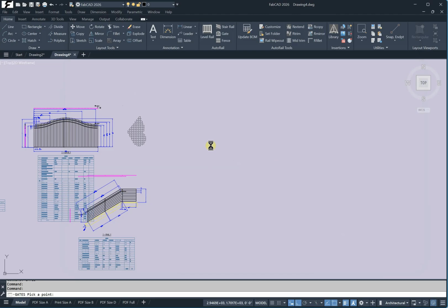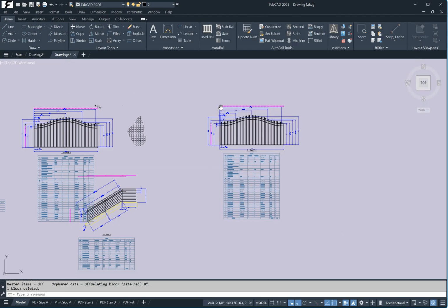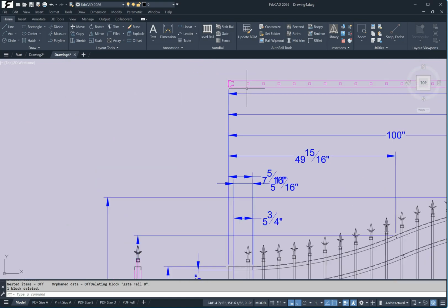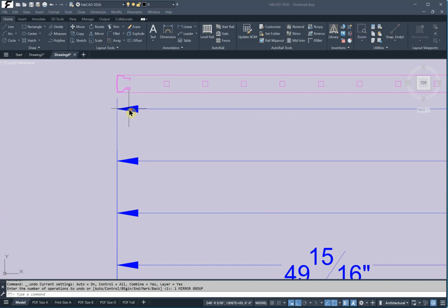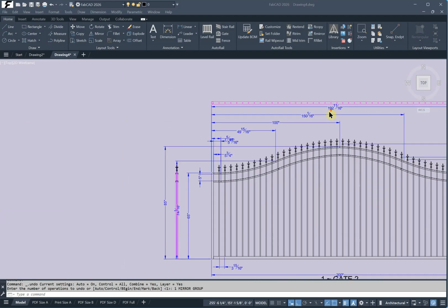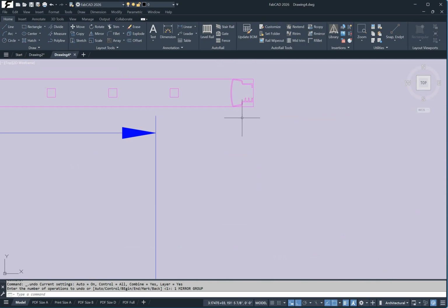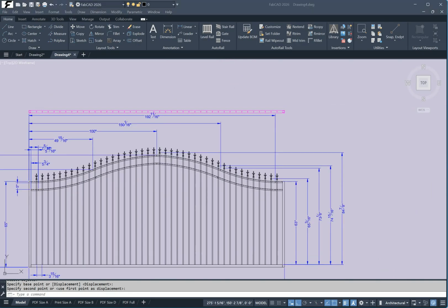Okay, we'll draw it. And you'll see there's the custom shape on the end. When you check out the plan view, you can see the extrusion here. But on the other side, it actually faces the same direction, so you're going to have to mirror it real quick. And you're ready to go.